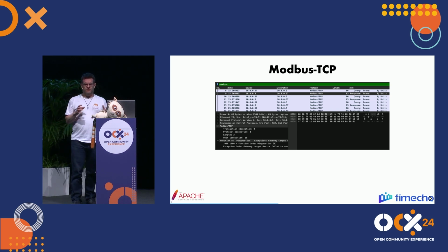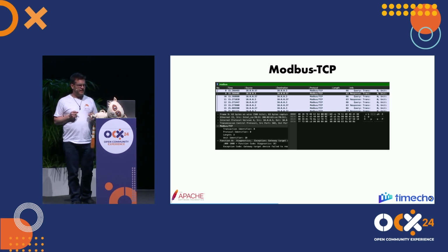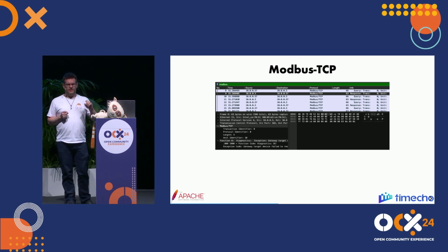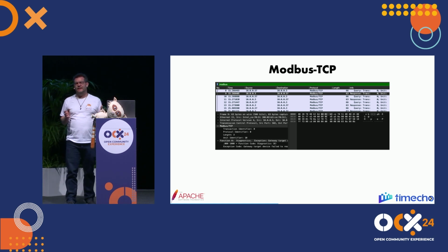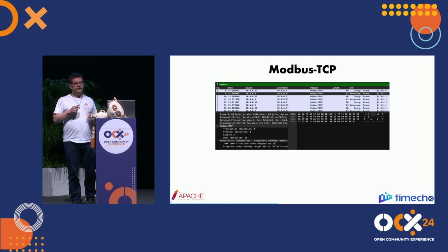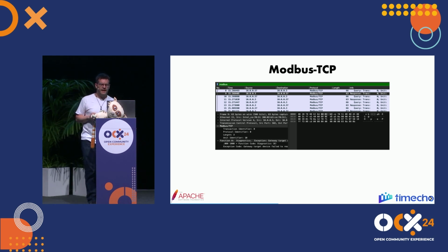So you're reading lots and lots of data. Being able to send a data packet in a quarter of the size, I think you can all imagine that with OPC you very soon reach the capability that your network infrastructure is able to handle. And that has actually been something I've come across very, very often.